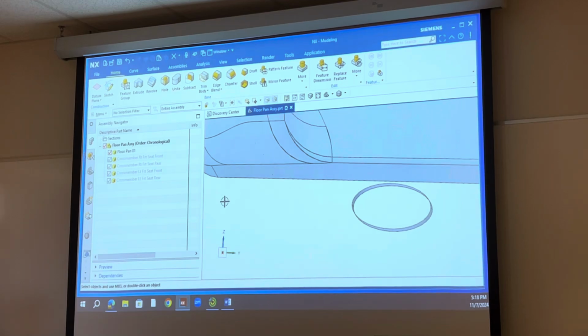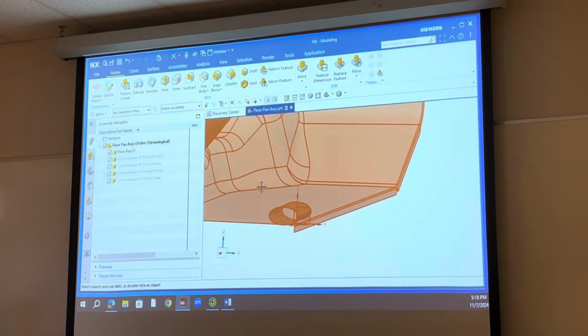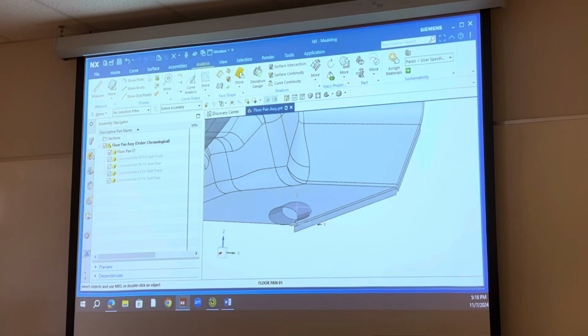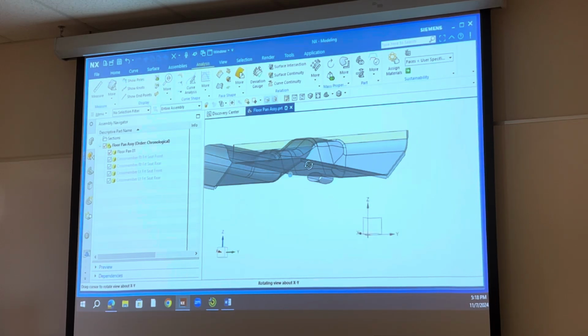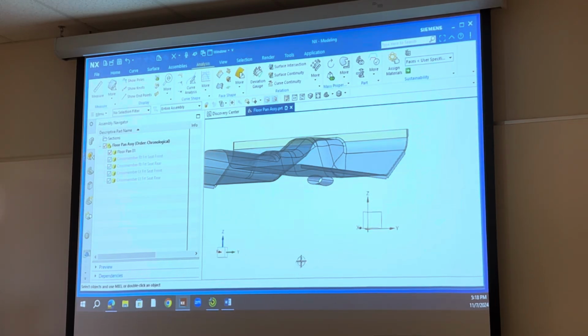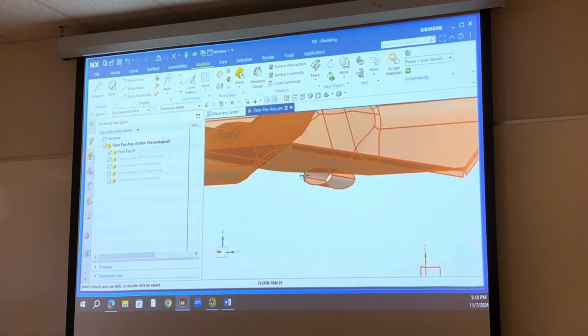Well, in an older version of NX, I had you go to a tool under analysis called Measure Extreme or Extremum, but they don't have it here anymore, okay? They do have, in the Measure tool, a tricky way to do that, but I was having a hard time writing it up and getting it to work right when I rewrote this exercise for NX 2212. I will show it to you though, I kind of figured it out. I could go back and change this again, but let me do it the way I tell you to do it. It says, I need to make a plane that's flush with the top of that part.